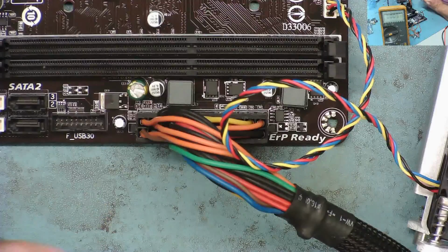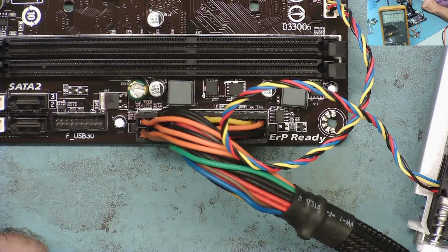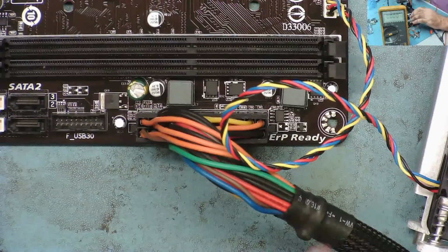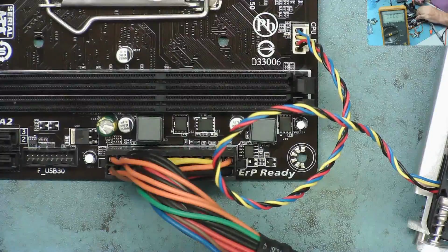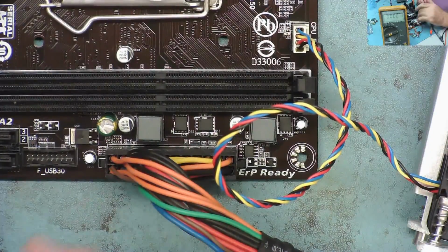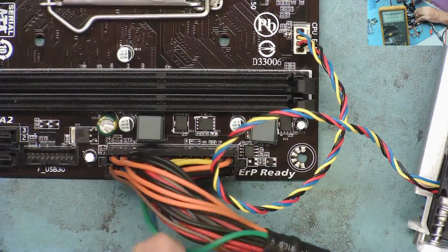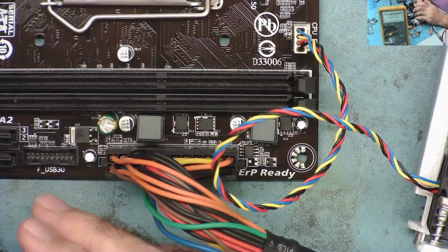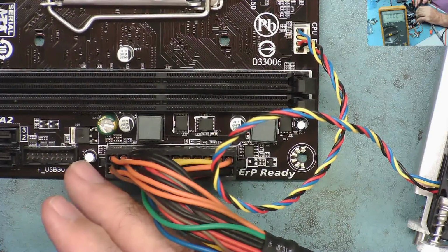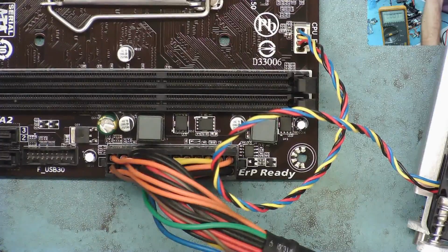Okay, I'll just switch the main power off. Let's give it a spin once more while the power supply discharges. Nah, it's done. I don't think that's happening because there's any sort of overload anywhere. I think that's happening because for some reason the motherboard's telling it to shut back down. But what we can do is compare with the known good board and check the resistances on all the main voltage supplies, and let's see if there's any difference. Personally, I don't think there will be.